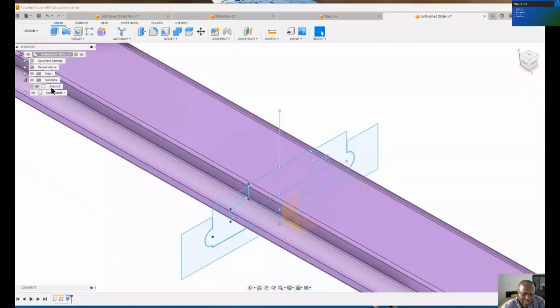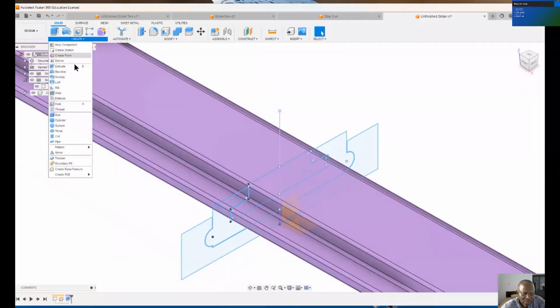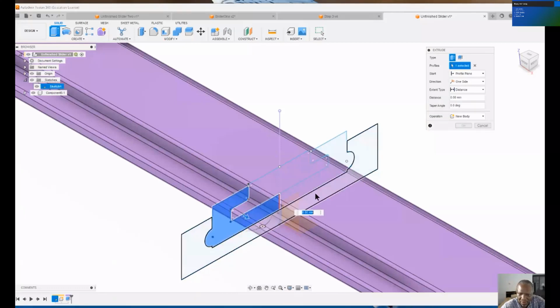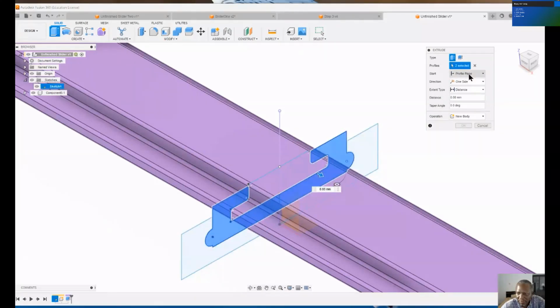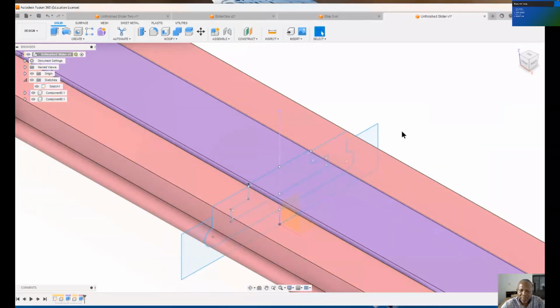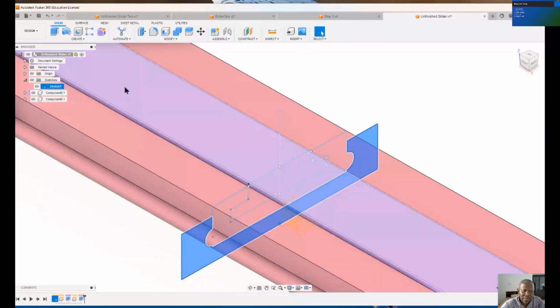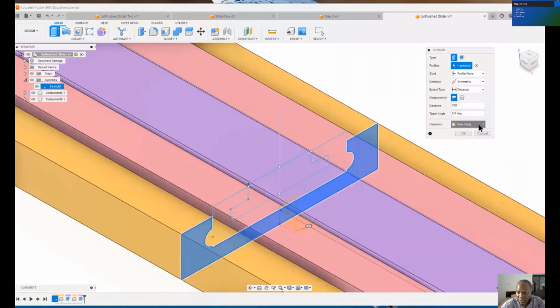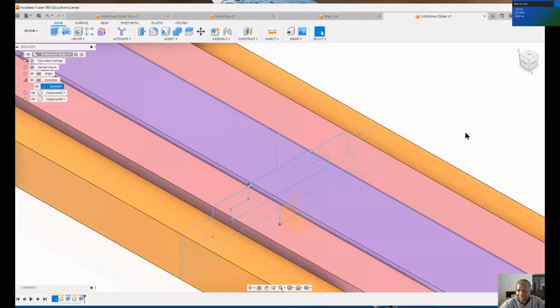In order to get the second component, we have to turn on the sketch again. So to get the second component, we create extrude as before. Select the cross sections for extrusion. Then profile plane, both sides symmetric, 200, 200. And then we are creating a new component. That's okay. Lastly, we decide to select that one and we create an extrusion on it. And it's already selected, both sides symmetric, distance of 200, and we create a new component, and that's okay.